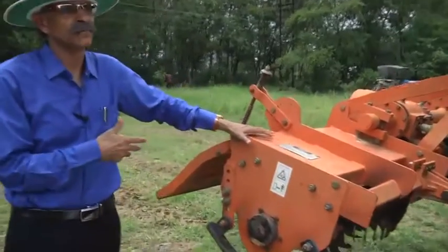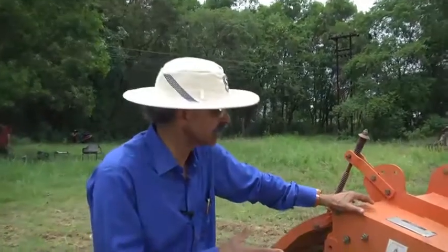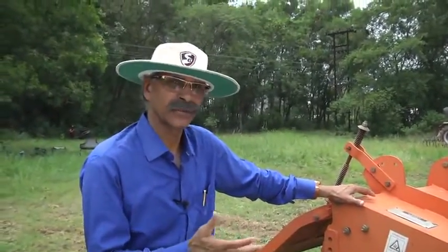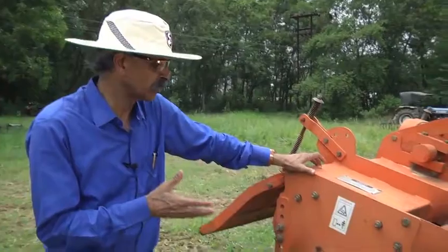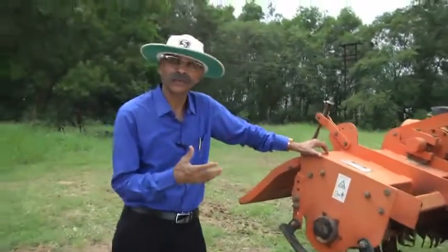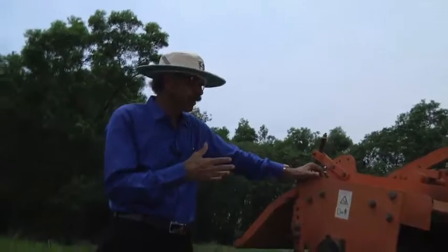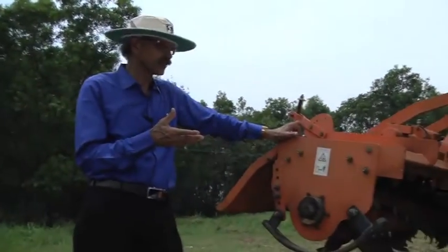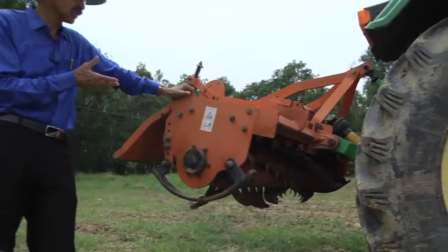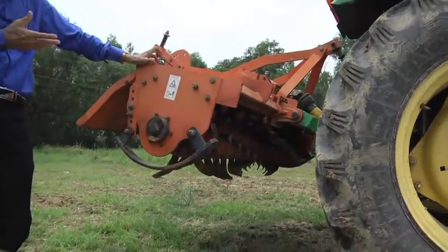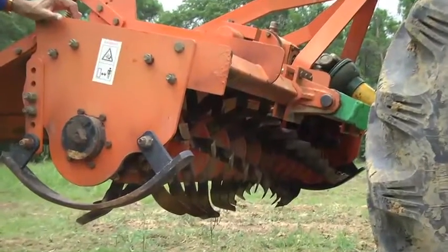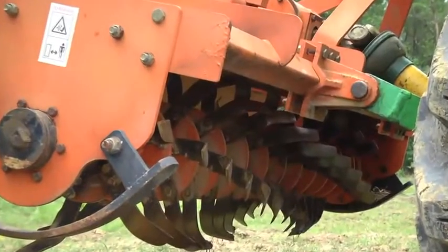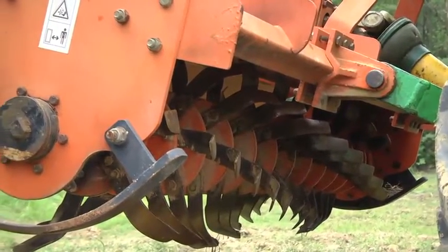Because earlier we had to have a primary tillage implement, then a secondary tillage implement, and twice or thrice operation of these, so the energy requirement is very high to prepare the soil before seeding. Now, this has become very popular because it does not require several operations and several passes. In fact, after harvesting of the crop, you can operate this and then prepare the field for sowing. In many locations we are operating this equipment, particularly where the soil is not very hard, and it is very popular, saves energy, and has all these advantages.